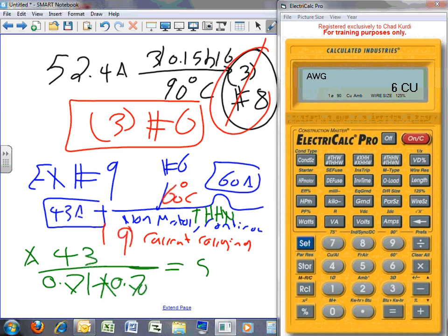86.87. So we came up with 87 amps. Now we're talking. Can you guys see how the derated amps became so high? Because now I need to size the conductor based on 87 amps. Cool? Phil, did you guys come up with the same number like my friend Chris?